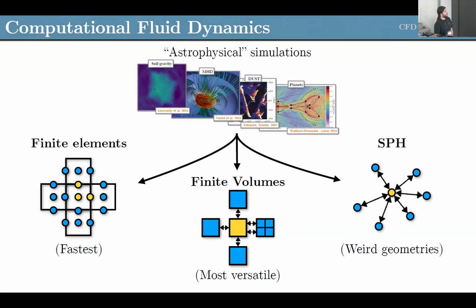So now that we have some hydrodynamics, there are multiple ways of actually performing such a simulation. On one side, you have finite difference methods, where you just discretize your simulation and also discretize the differential operator, and you get a simple scheme in general, which tends to also be the fastest kind of scheme for hydrodynamics. Now, if you want to resolve shocks accurately, you will need to move to another method, as finite differences are not that great for that. Typically, you will look at finite volume methods, typically the Godunov scheme, to properly resolve shocks.